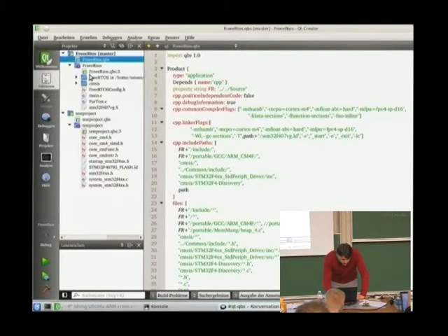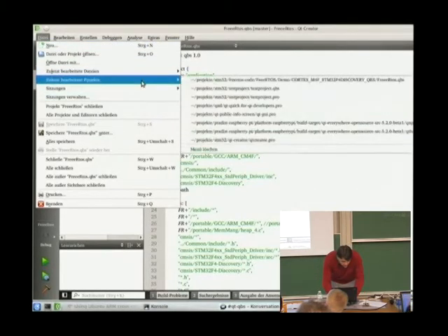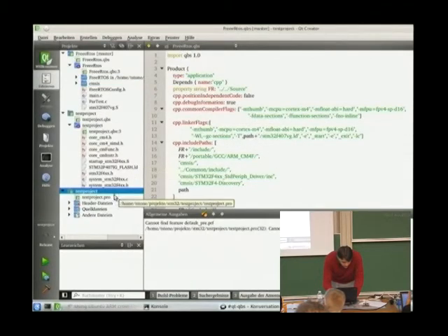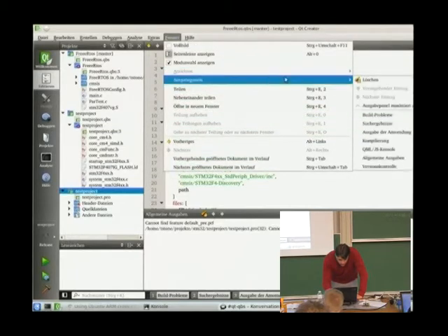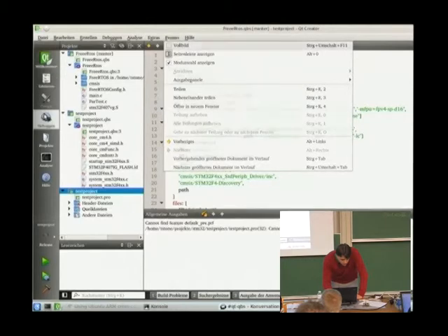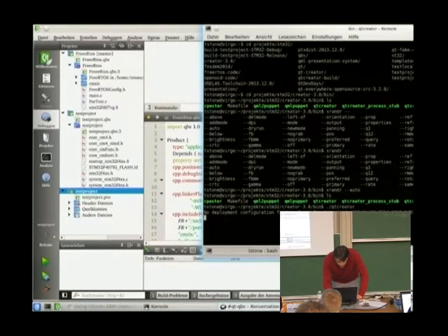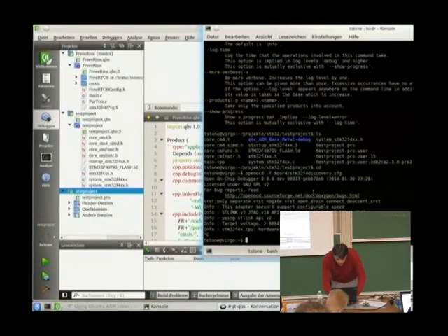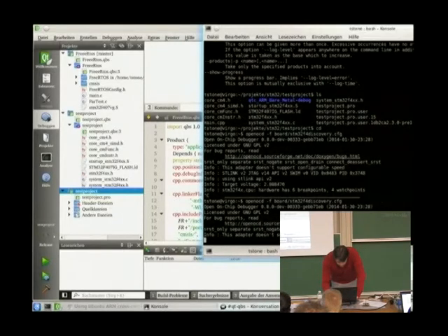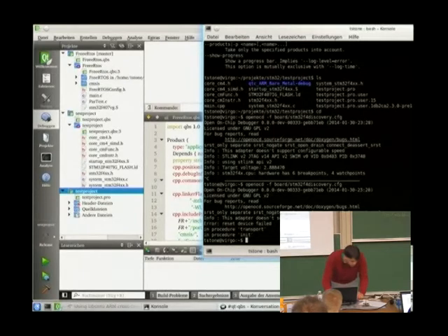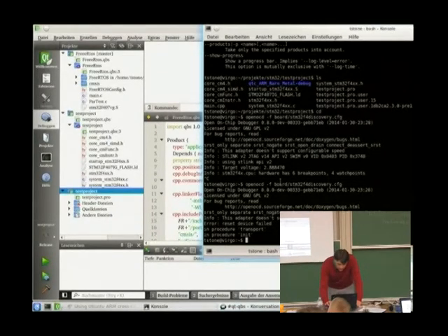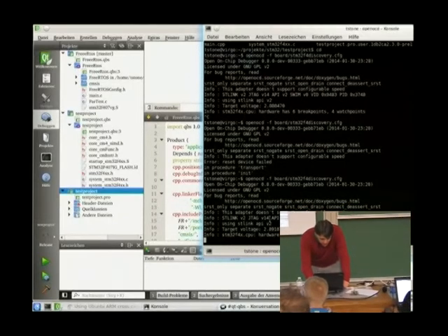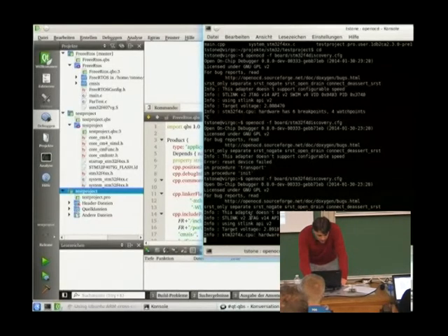Okay, and well, the FreeRTOS, I'd like to have it running, but unfortunately I didn't have enough time to get it up and running. And so I'm going to use the test project over here. To start debugging, I can switch on the debugger. Okay, it's switched on. I'm just going to see if I'm having the hardware debugger running. Oh no, it's not running. So I have to start OpenOCD in the background. Okay, now it's up and running. It doesn't like to be hibernated or something like that.